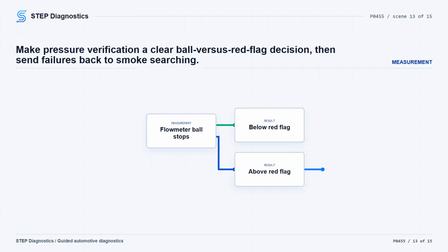For Phase 1, calibrate the flow meter using the 0.020 standard according to the tool setup. Connect the supply hose to the vehicle through the suitable adapter and set the leak detector to the 0.020 standard. Turn the ignition on. Close the canister vent valve by commanding EVAP on at 100% duty cycle and start the pressure supply.